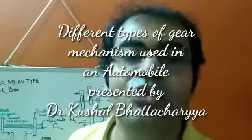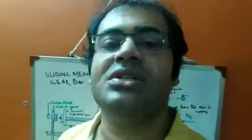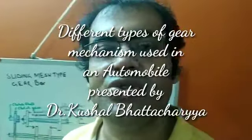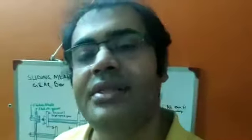Today I will be discussing the sliding mesh gearbox. In the previous lecture we discussed the requirement of the gearbox: for different road conditions or gradient conditions, the torque requirement also varies. The tractive force also varies, and we have seen that the first gear will provide the maximum amount of torque, then the second gear, and then the top gear.